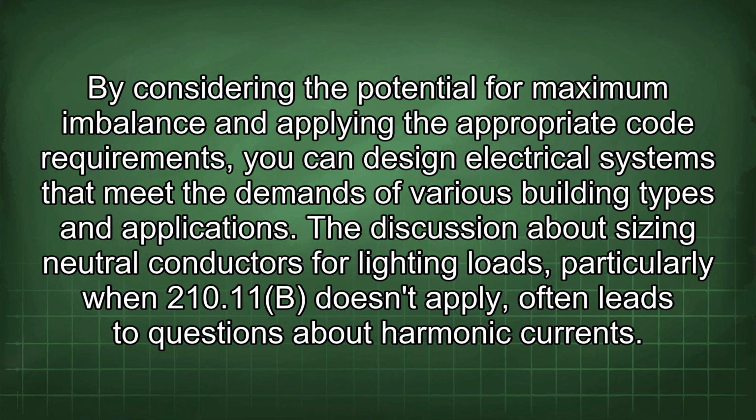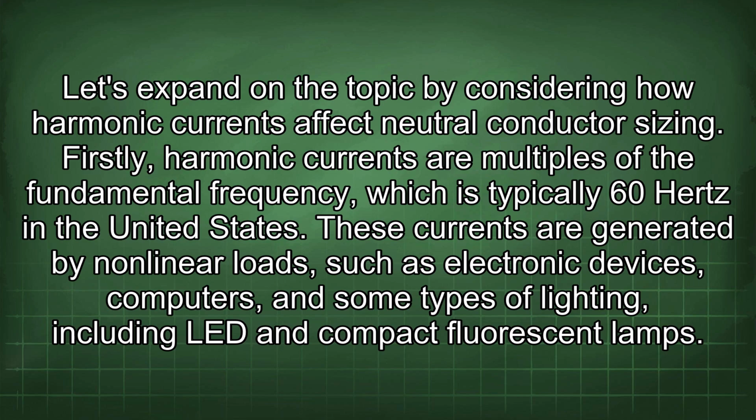The discussion about sizing neutral conductors for lighting loads, particularly when 210.11(B) doesn't apply, often leads to questions about harmonic currents. Let's expand on the topic by considering how harmonic currents affect neutral conductor sizing. Firstly, harmonic currents are multiples of the fundamental frequency, which is typically 60 Hz in the United States. These currents are generated by nonlinear loads such as electronic devices, computers, and some types of lighting, including LED and